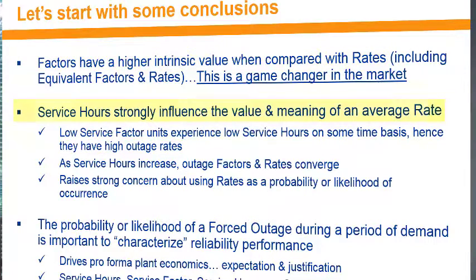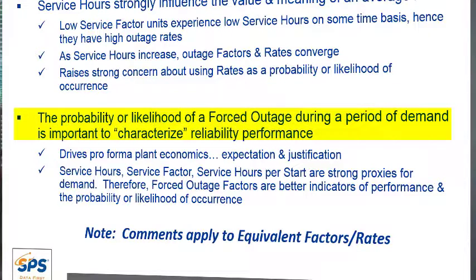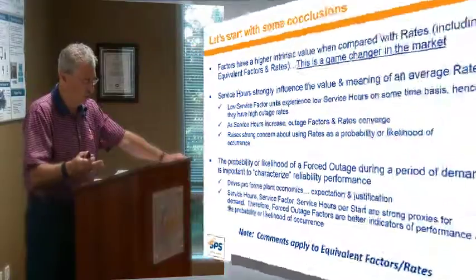Second, rates are greatly influenced by service hours, generating time. I question the use of rates as a probability, unless service hours are treated as a proxy for demand. Third, understanding and quantifying the likelihood of a forced outage during a period of demand is still important to our industry and market. EFOR and EFORd just do not provide meaningful measures. They're meaningless. There are other alternatives, and I'll show you what they are. You should know about them.